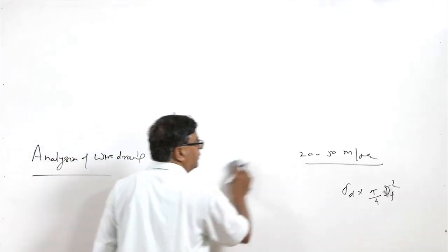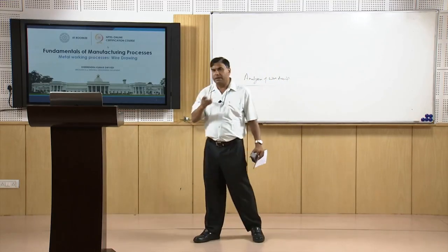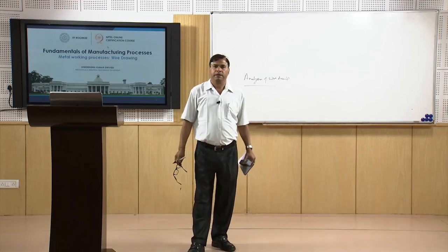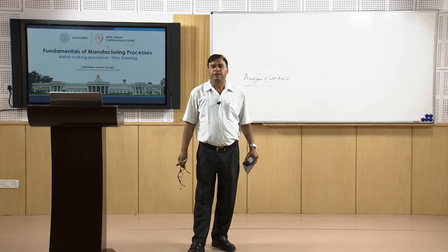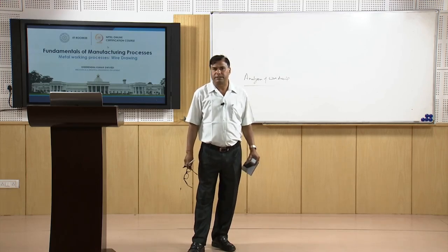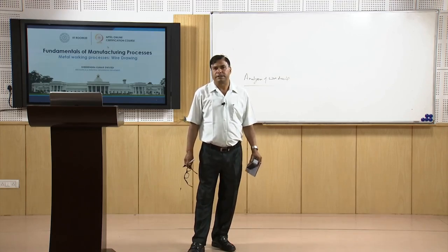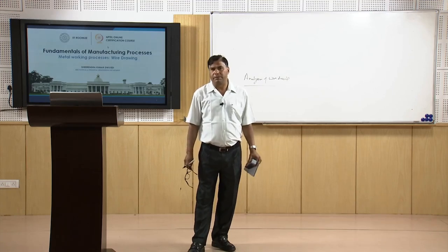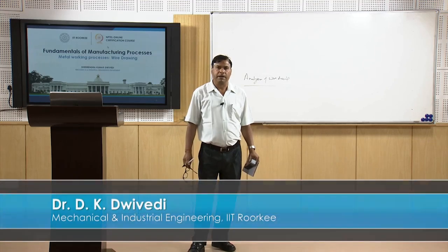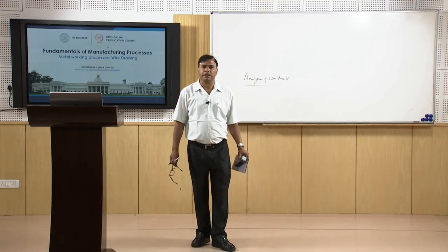Now, here I will summarize this presentation. In this presentation, I have talked about the purpose of wire drawing, and the factors that affect the success of wire drawing, and thereafter we have also seen how the different aspects related to the stress and power and the reduction ratios related to wire drawing can be determined, to understand the way by which wire drawing will behave and act during the deformation process.